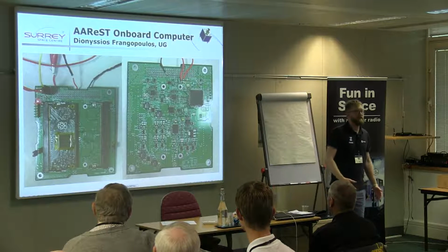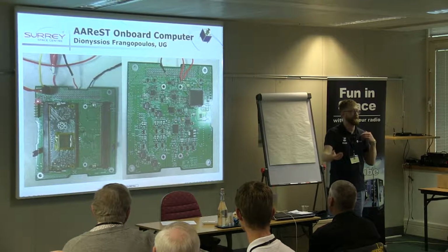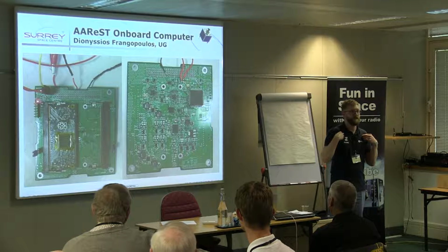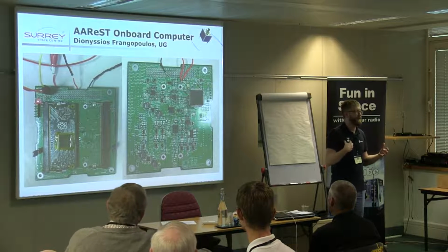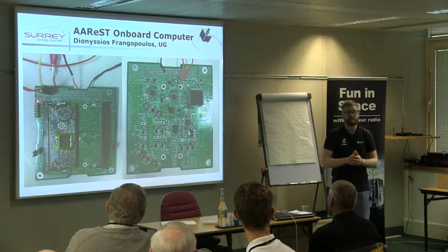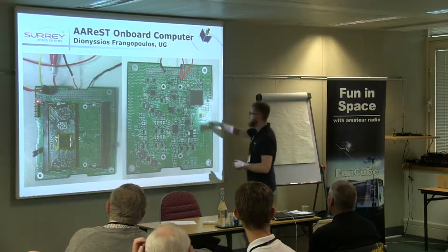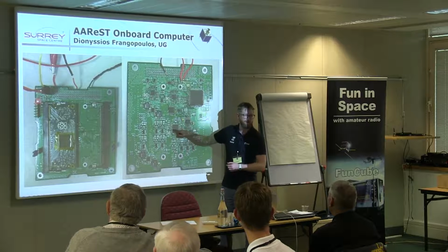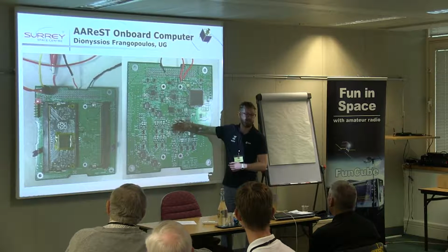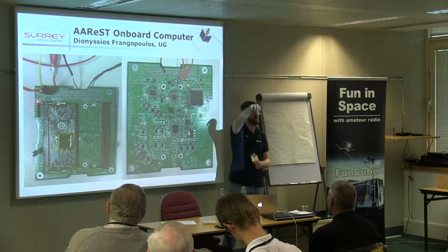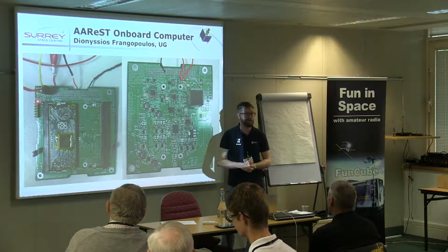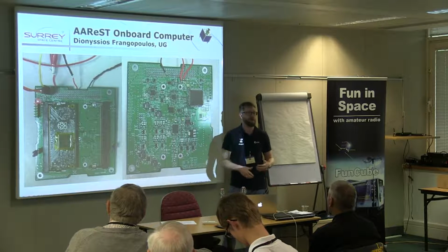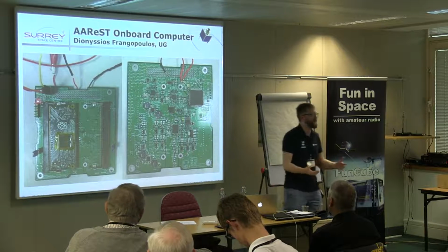So what happens is we get I2C coming in from the platform, but also the Raspberry Pis are masters as well, because they control some of the payloads to do the rendezvous and docking maneuvers. That then controls, with switches, the RF systems, because we have 3 sets of these computers on each of the different satellites. So these act not only as our inter-satellite link, but really as payload managers. We call this the payload interface computer.